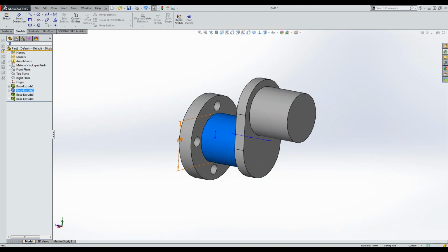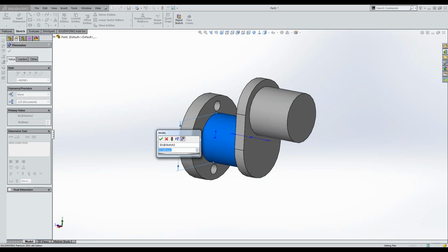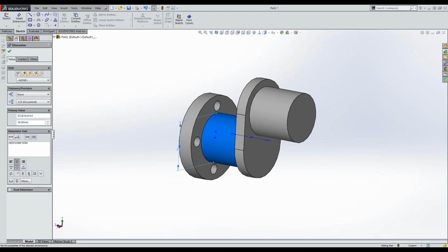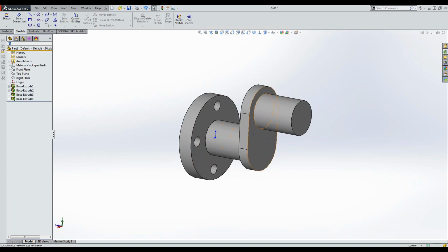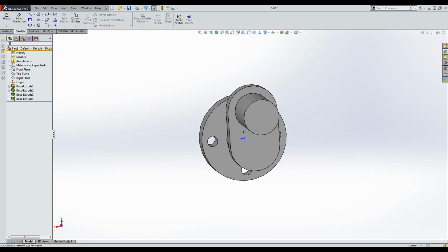So what I want to do, though, is make sure that no matter what I do, that offset is always maintained at 10 throughout the whole part, just to keep it uniform, and that way later on when I make a change, I don't really mess up the model from doing that. So what I'm going to do is create an equation.